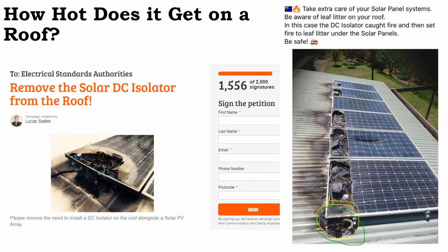It's like, okay, well, there's roof-mounted air conditioning units and commercial settings have disconnect switches. The problem with a disconnect switch on a rooftop is not the switch itself, it's the roof. It's a very hot environment. And by cutting that wire inside that disconnect, you're inserting a failure point into the system. And the terminals on those boxes where the cable hits the box is one of the hottest points on the system.